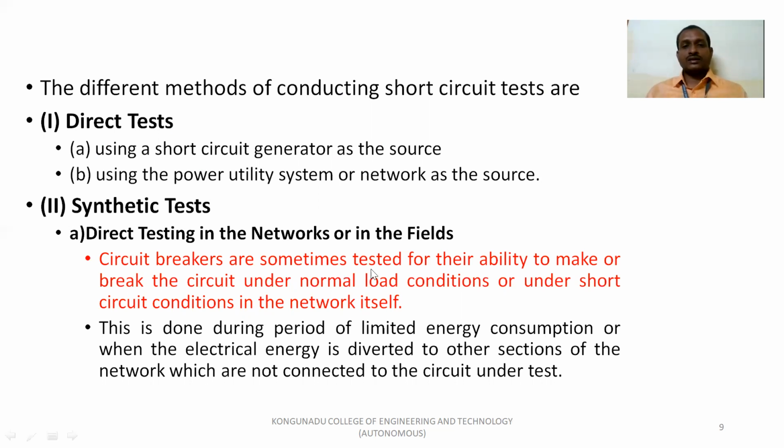Circuit breakers are sometimes tested for their ability to make or break the circuit under normal load conditions or under short circuit conditions in the network itself. So we are going to test the equipment under normal load conditions or under short circuit condition in the network itself. This is the short circuit testing in the networks or fields.